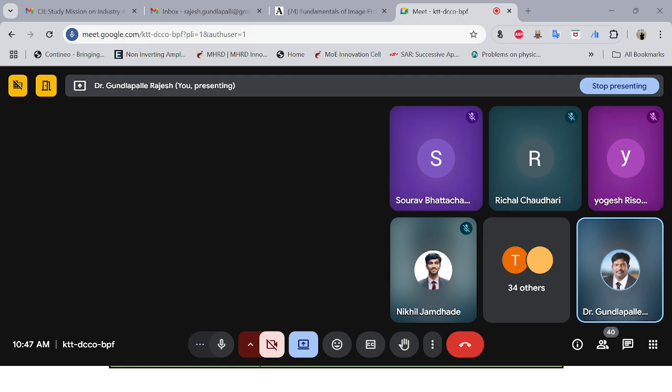If you want to transfer or load multiple data using a single instruction, then you will use these multiple load and multiple store instructions. So load multiple data from the register list to the register RD. It reads the multiple words from the memory location specified by the RD, and increments after each and every transfer. So, 16-bit instruction.